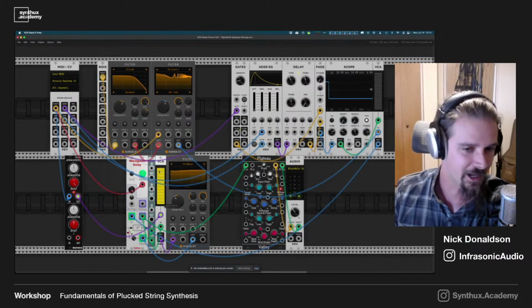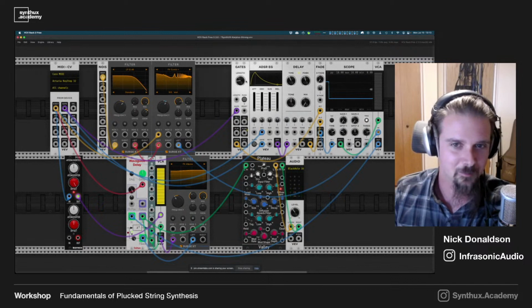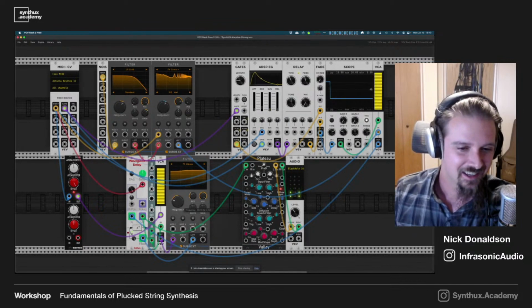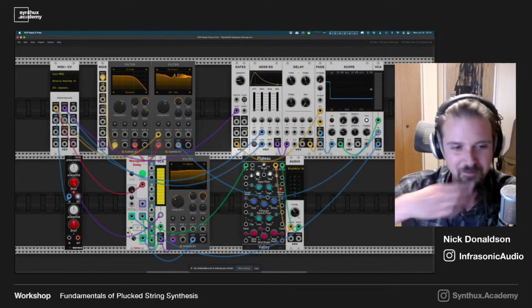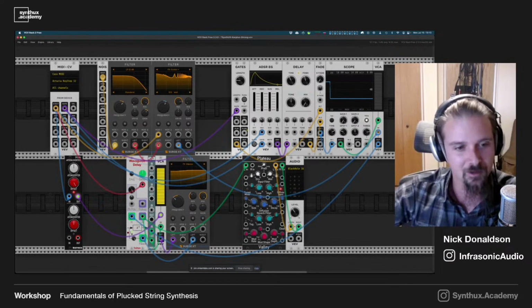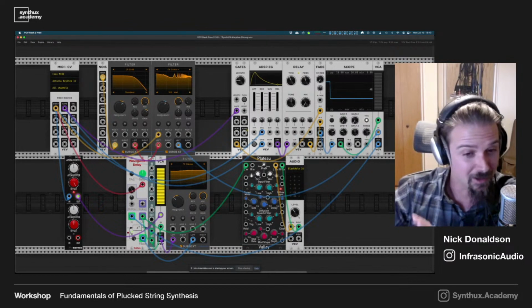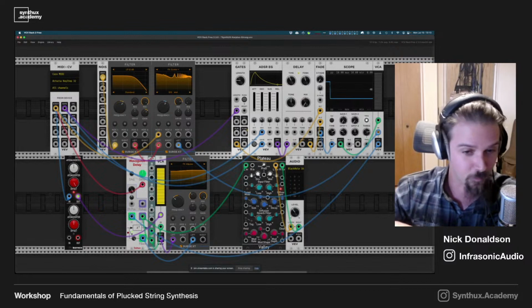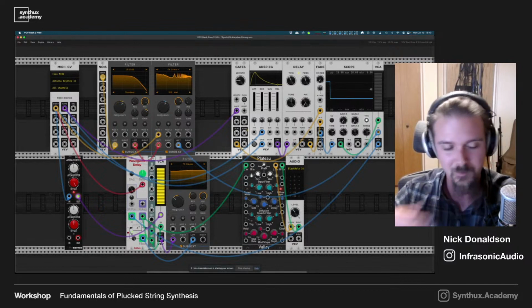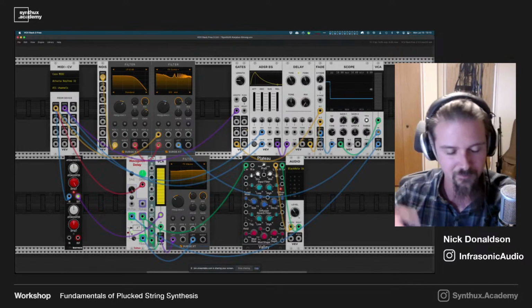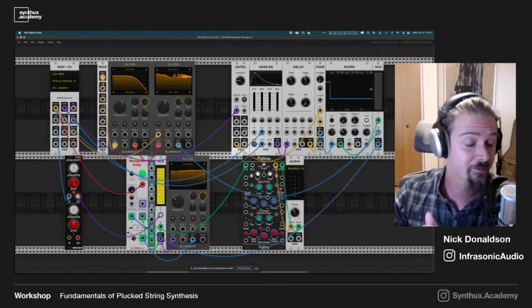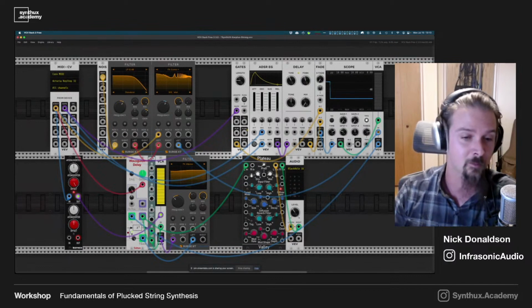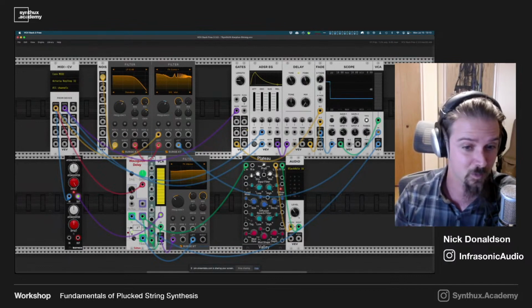So it gets really inharmonic. It just sounds kind of, yeah, like that's because the different harmonics of energy that are building in our waveguide have different amounts of delay based on the all-pass filter. It's really messing with the phase delay or the phase response of the feedback system. So different harmonics end up getting different amounts out of tune from actually being harmonics. So the resulting sound is quite inharmonic.